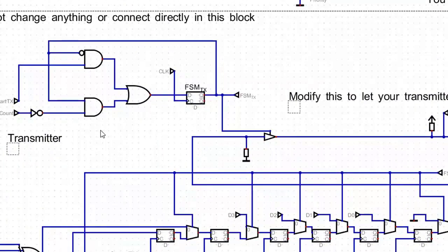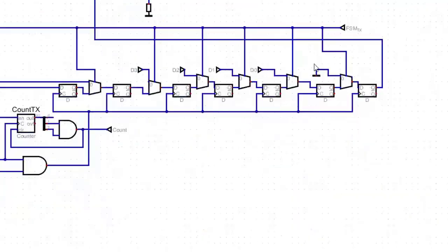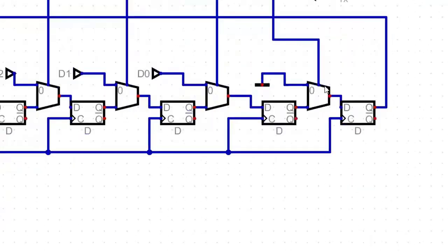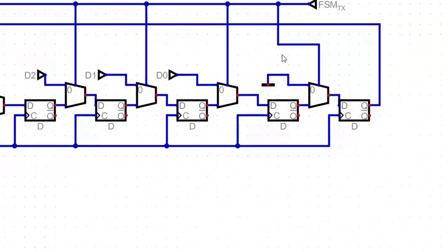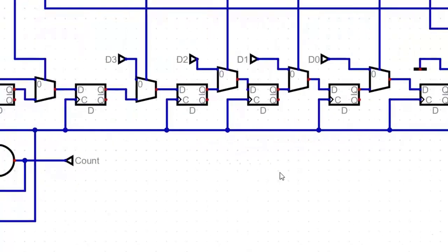I don't have the time to go into too much detail, but from what I see here, this should be fine. Why do you say it doesn't work? Oh, okay. I think because my problem is immediately after the start signal gets sent. So I think I'm a clock cycle behind. I think this 0 goes once in here, and then it needs another clock cycle for it to go onto the serial line.